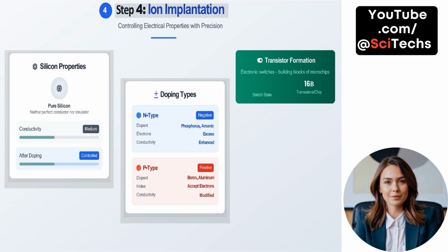Step 4. Ion implantation. Ion implantation is used to precisely control the electrical properties of silicon by introducing dopant atoms. Pure silicon has medium electrical conductivity, making it neither a full conductor nor a perfect insulator. After ion implantation, this conductivity is finely tuned based on the type and amount of dopant introduced. There are two primary doping types, N-type and P-type.